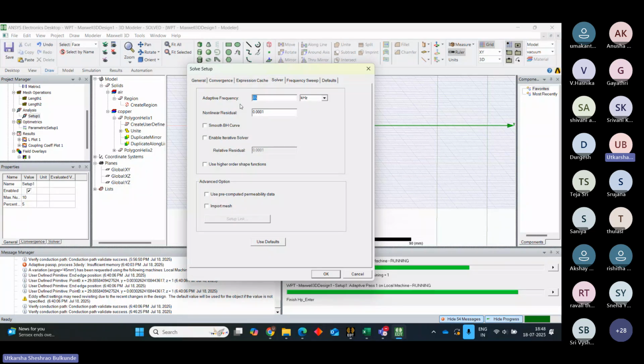There is one standard available for it, we call it J2954. According to that, your frequency should not exceed about 90 kilohertz. So that's why most of the time I analyze it for 85 kilohertz, but you can keep high frequency also. It's just an analysis part. You are not dealing with any application for now, right?